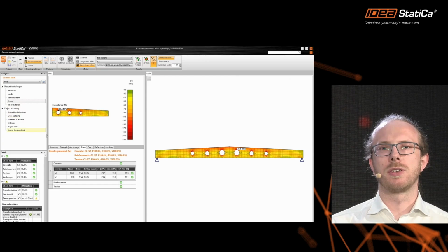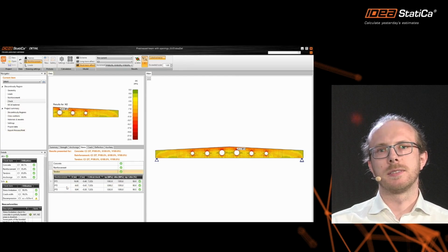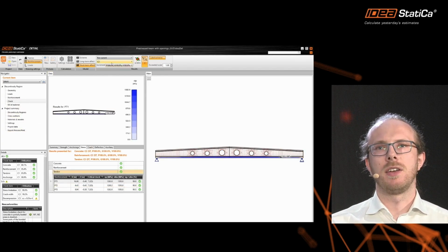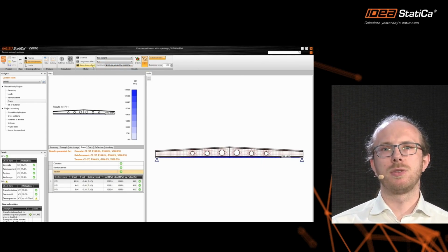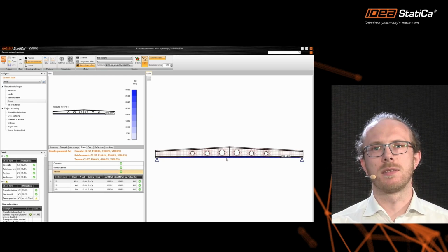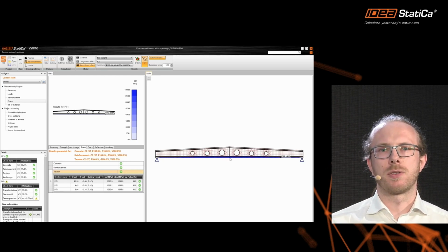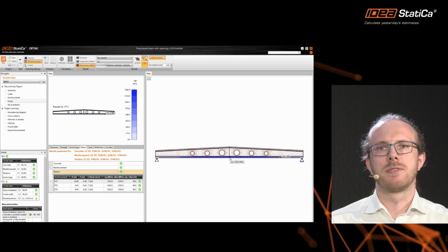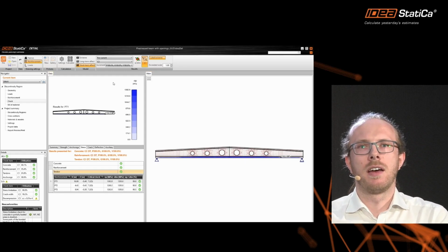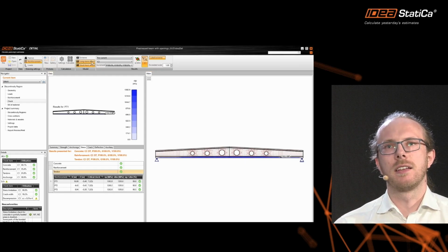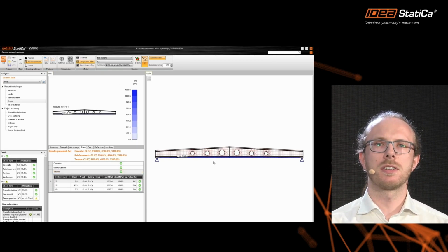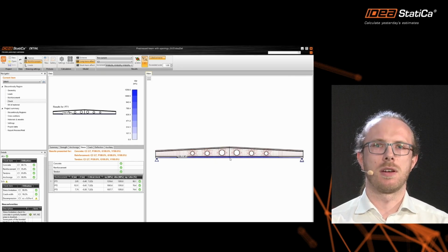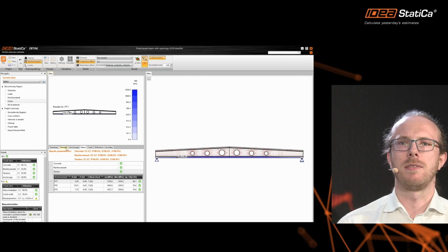If we go to see the results, you can get the application to display 2 types of stress in tendons. The first type is for short-term behavior and the second is for long-term behavior. And the important thing is that both of them are for just one combination. So it basically means that you don't have to create a special combination for long-term and short-term behavior.